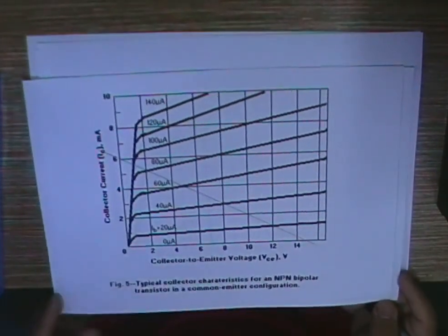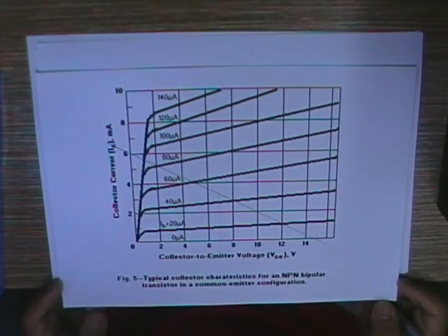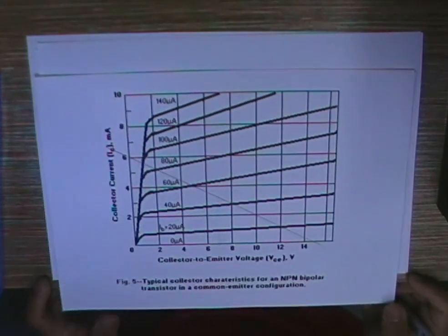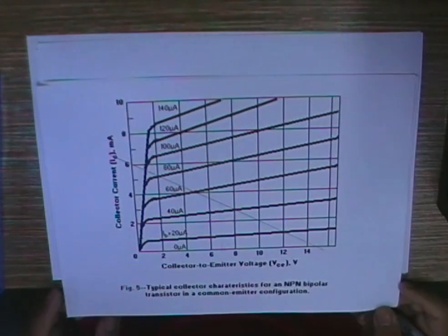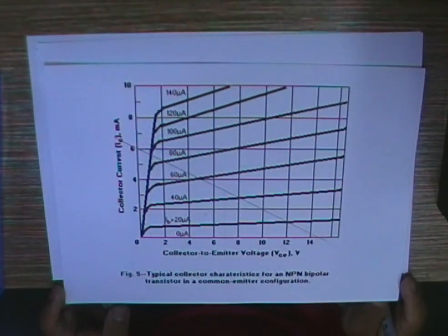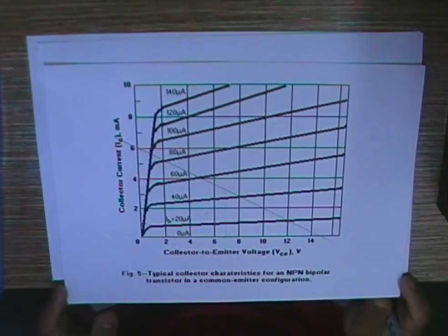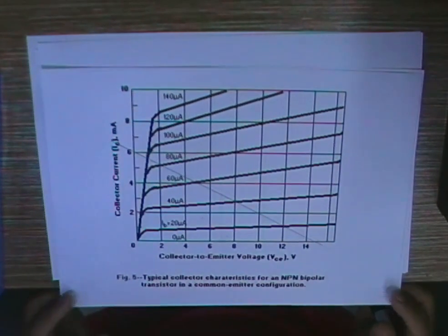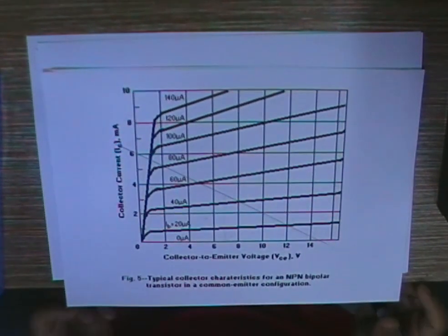If voltage divider doesn't work, you have to change your design into fixed bias, which will give you very high gain but very easily falls into saturation. Typically, you use a fixed bias when your gain is very high and the signal is very small. The signal is in the range of maybe tenth of milliamps, or maybe less than that, and you need a very high gain.